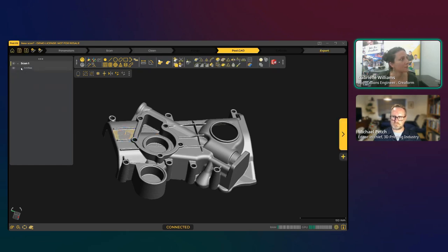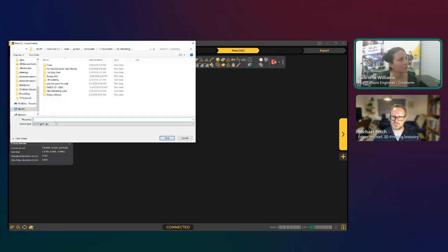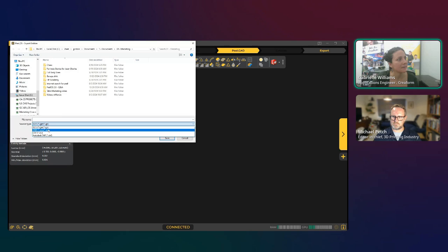As I was doing here, you can just right click, export selected entities, and then save it however you need to, which I believe Onshape takes, IGES files and step files. And then from there, you would import those items into Onshape and build from there.